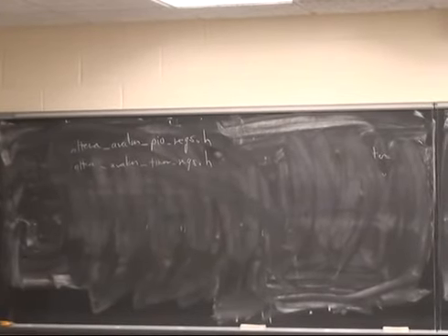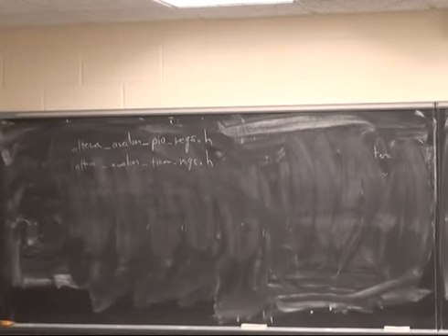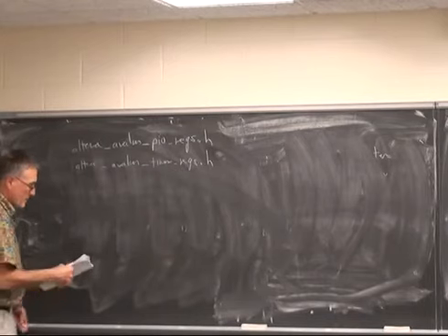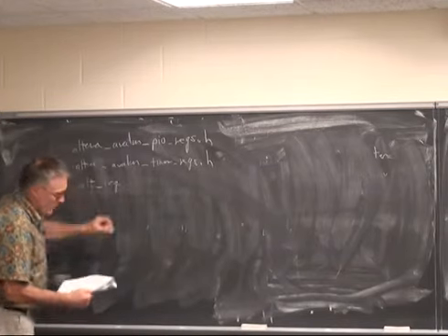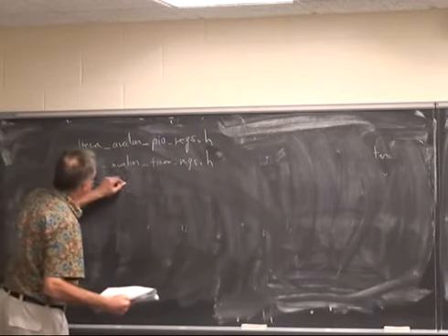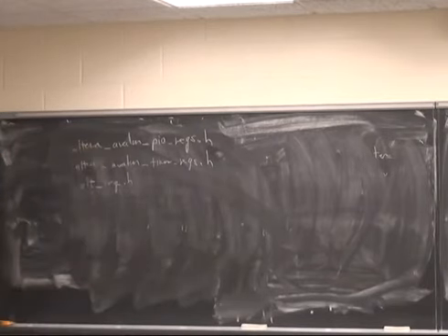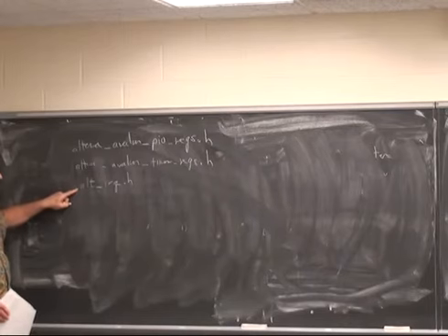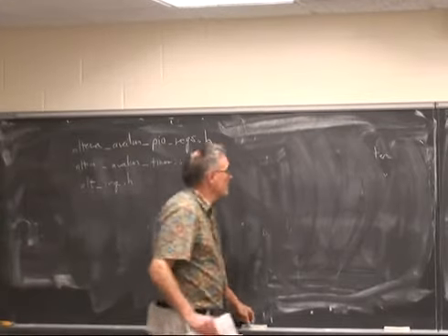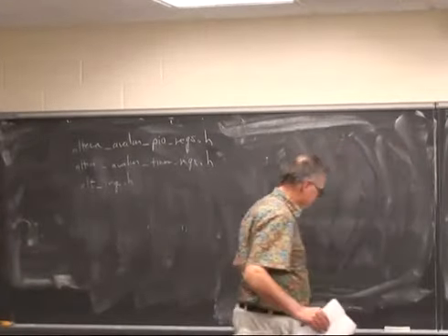There's also another file that I found essential, and that was alt_irq.h. These are register level, but this is a HAL level header file. I found dealing with the interrupts at the HAL level was easier. But you may need to look at that header file also.